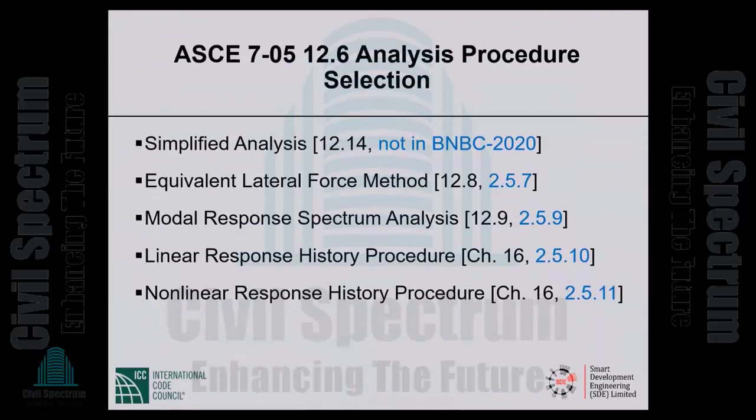Next part, methods of analysis. In ASCE 7-05, there is a simplified analysis supposed to be standalone. You don't have it and you are better off without it. I never thought much of that simplified procedure and it's a waste of time to talk about it. So let's forget about that. Equivalent lateral force method, section 12.8 of ASCE 7-05, your section 2.5.7. Modal response spectrum analysis, 12.9 of ASCE 7, BNBC 2.5.9.